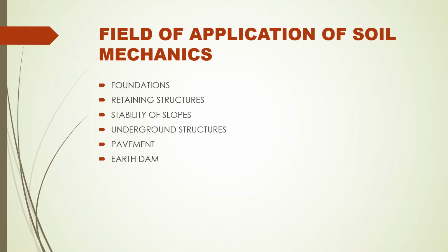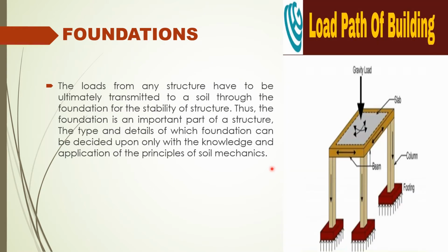Field of application of soil mechanics: foundation, retaining structures, stability of slopes, underground structures, pavement, earth dam. The load from any structure has to be ultimately transmitted to the soil through the foundation for the stability of the structure. Thus, the foundation is an important part of a structure. The type and details of the foundation can be decided upon only with the knowledge and application of the principles of soil mechanics.